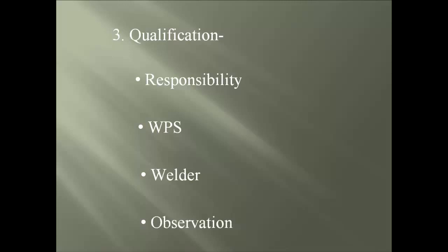And lastly is the area of compliance using the approved documents, specification, and codes, which is only done by the observation from the quality control and quality assurance professionals. The QC or QA professional that is responsible for the acceptance or rejection of the material or workmanship should have training and experience with metal fabrication, observation and testing in both the shop and field areas, and if required by the authority having jurisdiction, the proper certification. The proper observation sequence items should be as followed.